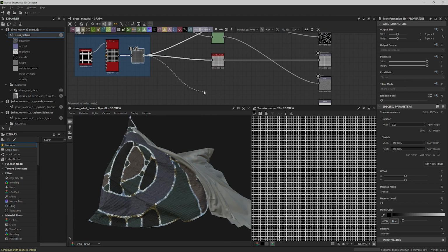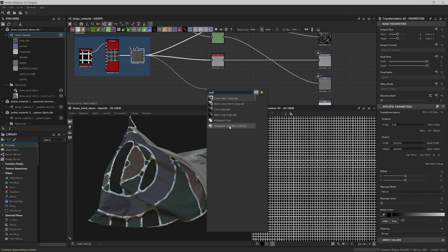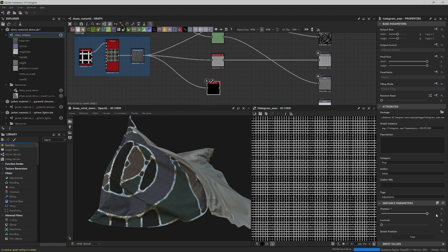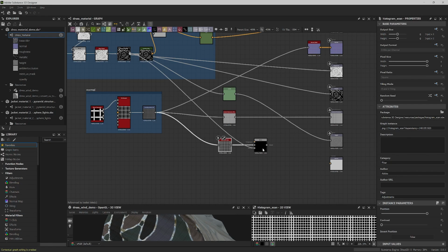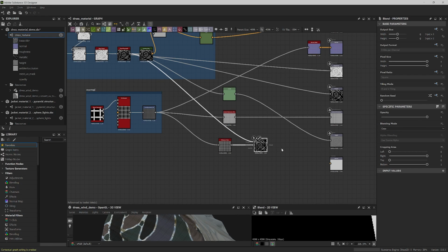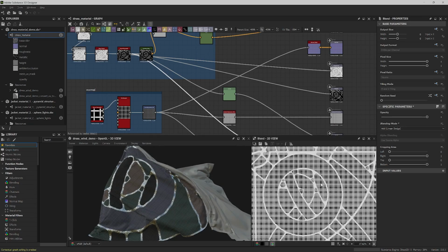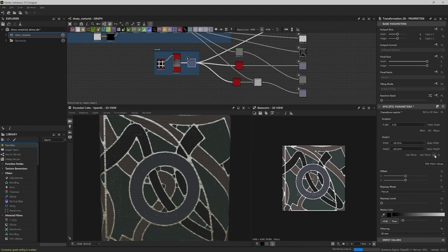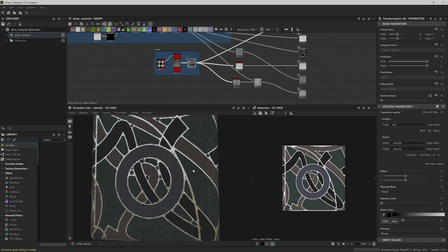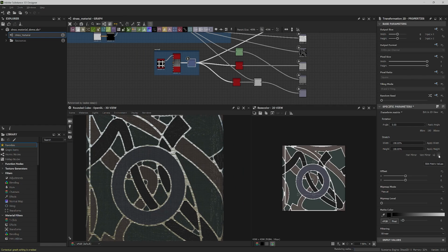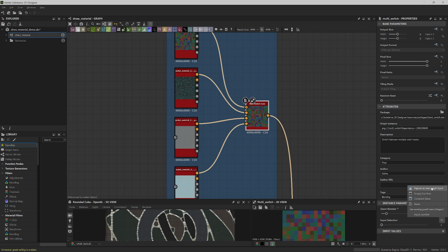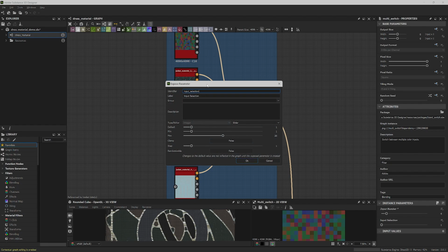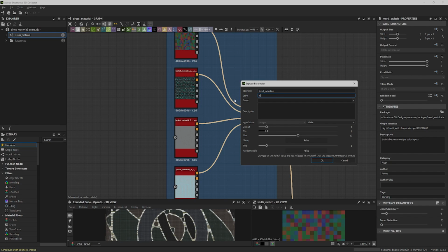Let's now make an opacity mask to plug into our opacity output. By connecting the weave to a histogram scan and using a blend, we will create a mix of the weave with the dress print. This ensures that the metallic outlines remain fully opaque. I applied the material to a cube to visualize it more easily. Playing around with the 2D transform node allows us to test how well the transparency works by multiplying and dividing the weave by 2. Next, let's expose some parameters so that we can later use them in Painter or in other programs through the Substance plugin.